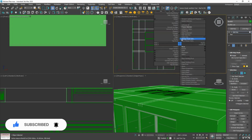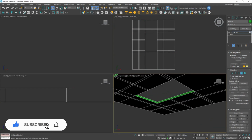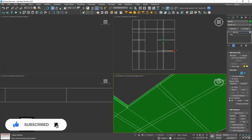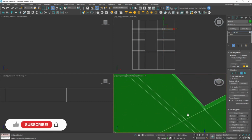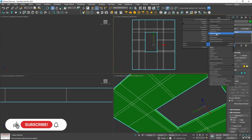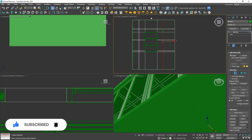Now if we right click and hide unselected, you can notice we've only now got our ceiling selected. So we want to go and just select where our lights are. We can turn off snaps as well to make this a little easier. And I'm holding Control to keep our current selection and select some more lights. And I think I've missed that middle one actually, so let's unhide all. Oh, I missed two of them.